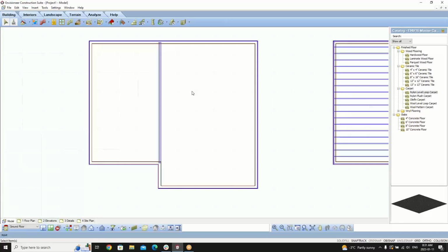So in today's class, we went through and looked at the various options for inserting structural floors and inserting floor framing in Envisioneer. Some points to remember. The structural floor tool will insert all of the components of the floor based on the properties of the structural floor that is selected. The structural floor can be modified to add in bearing lines, and you can also adjust the framing base point.